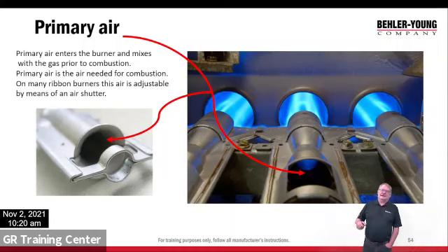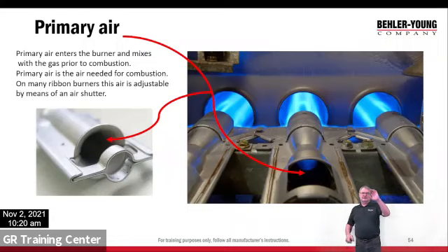Now the gas is going to come in through the back of the burner. If I look at the picture over there, you can see that little round circle. That's where the orifice would go, so that's where the gas would go. And that opening there is the primary air intake. So the gas is coming in the base, and air is going to come in around it. They're going to get into the venturi, where it's kind of narrow here, and that's going to mix the two. So the primary air and the gas mix, and then they shoot into the burners.